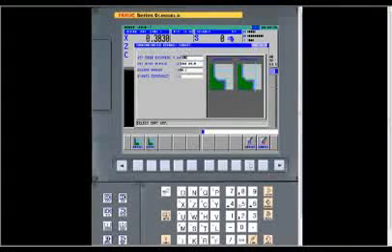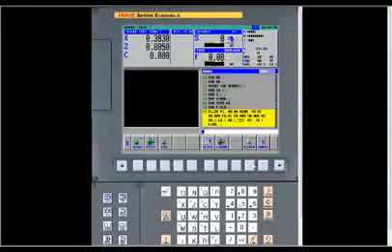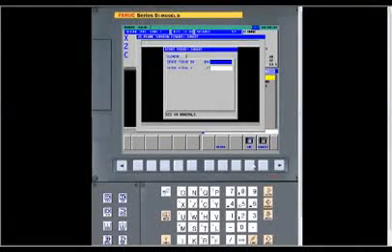Then we press insert because we filled out all the different tabs. All 3 are completely filled. We press insert and see what it does. As soon as you fill out the machining cycle, if there's any geometry that's to be associated with that, it'll force you into where you describe the geometry of the finished part, not of the rough stock, of the finished part, the finished profile. So for this, with the part we're describing, it wants the start point, and that's 0 and X, 0, enter, 0 and Z.